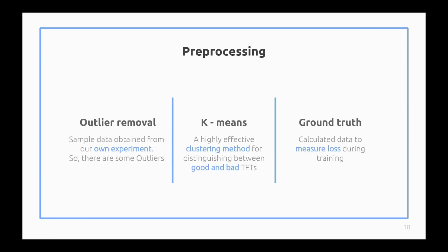The pre-processing proceeds as follows. Unlike the refined data obtained through TCAD simulation, our data were experimentally measured, and negative current values were sometimes recorded in the off-current measurement interval. These outliers were pre-processed using imputation with nearby values.